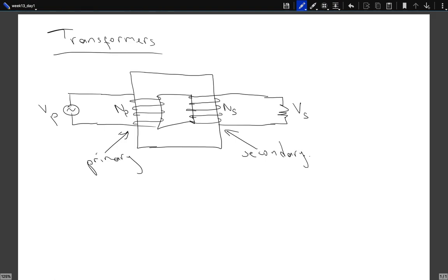Now, the idea is that you send some current, an alternating current, on the left-hand side. The alternating current creates a magnetic field, which is itself changing in time. So, in this solenoid, you create a magnetic field. And the iron, which is called a ferromagnetic material, the property of iron is that it first enhances the magnetic field, and secondly, it traps the magnetic field lines.